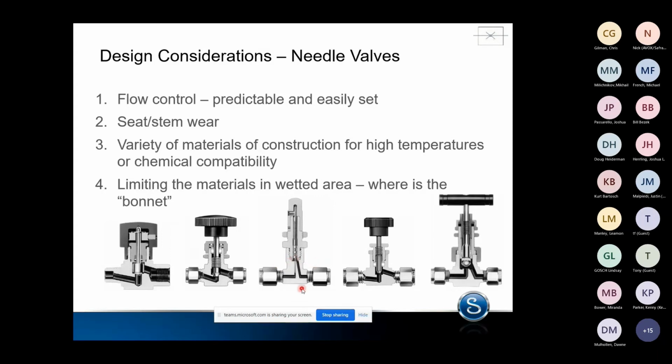So this valve, as delivered from Swagelok, is not capable of seating. There's a travel limiter set by the handle that prevents it from engaging with that valve body, so that without tampering on it, you're not able to break that stem off. But if you decide that you want to get a little bit less flow, you can tamper with the handle and risk shearing that stem off.